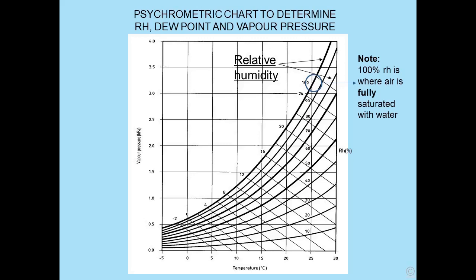It's at this stage that water will start to come out of the environment. So then, let's imagine it's 60% relative humidity at 20 degrees centigrade. We mark these on our psychrometric chart, where X marks the spot where the two factors meet, and then we project a line across to the 100% mark.